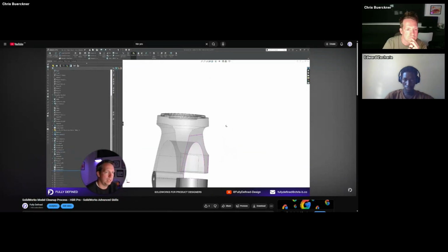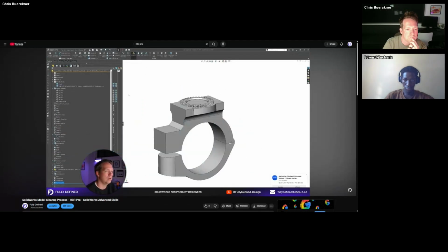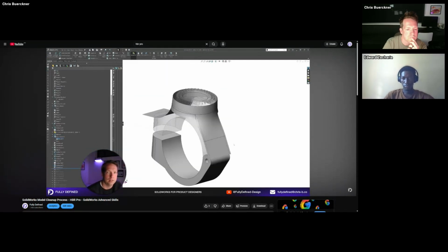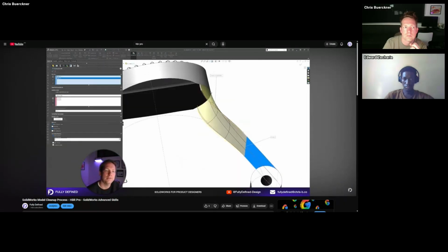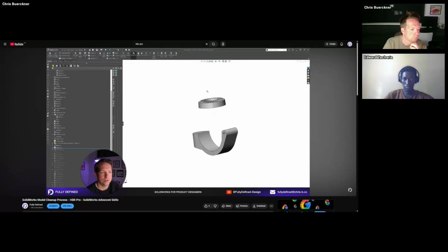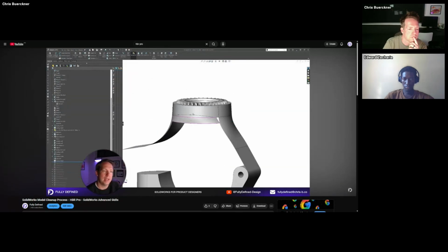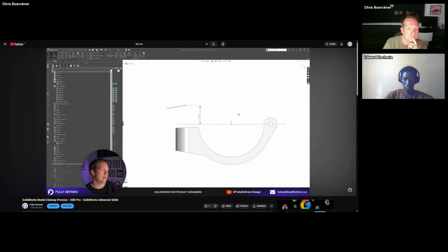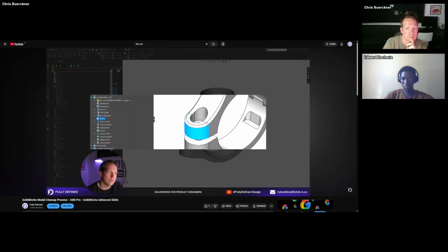The easiest features to pick out for reordering are edge features, think fillets and chamfers, used on the edges of your model, typically when the rest of the geometry is done. You want to move these to the bottom of your feature tree and stick them all in one folder. Where there are 2 fillets using the same dimension, if they can be achieved using 1 fillet feature rather than 2, then they should. Combine them, then delete the obsolete feature. Keep in mind that edge features used to make major changes to geometry should remain in order with their surrounding features. See example here. Fillet 32, which is a full round fillet done as part of the geometry for the clamp top.